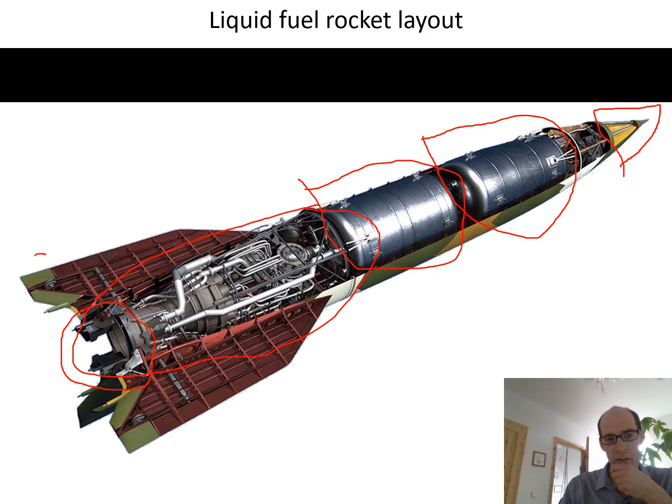And also, because it was an atmospheric rocket, it used aerodynamic rudders as well, particularly to guide the rocket once the engine had cut out and the rocket was on its more ballistic trajectory. Now, every other rocket since has actually gimbaled the entire rocket motor for a number of reasons.